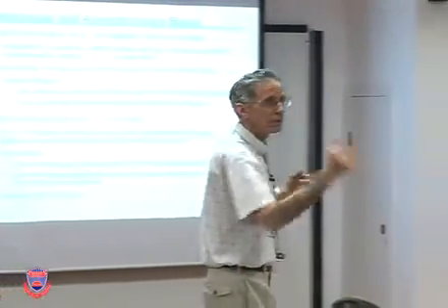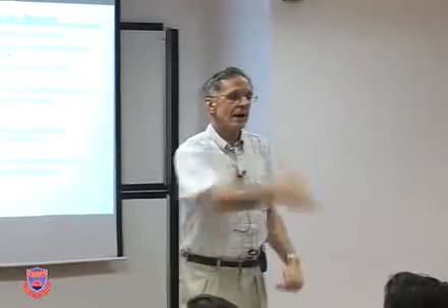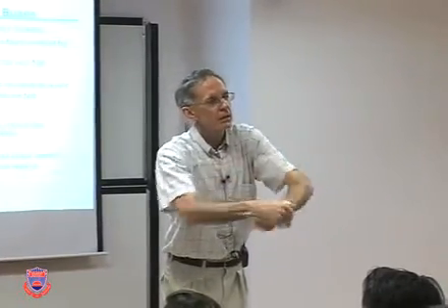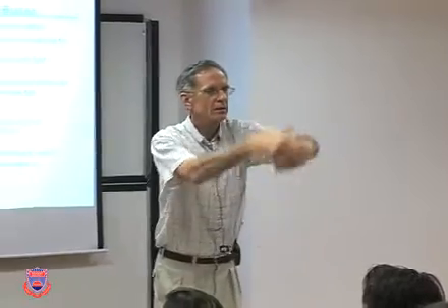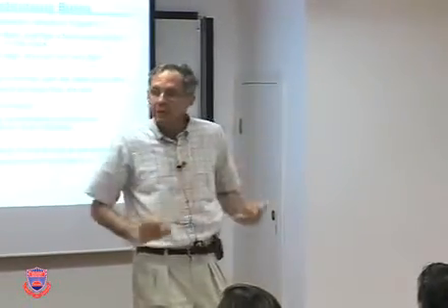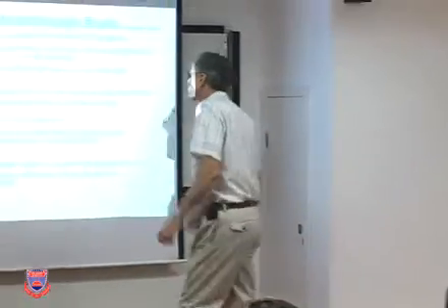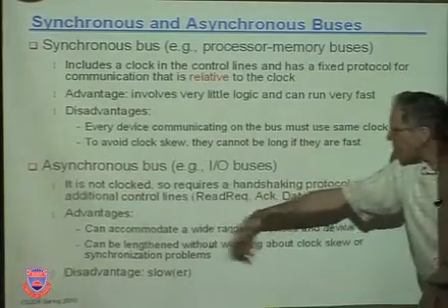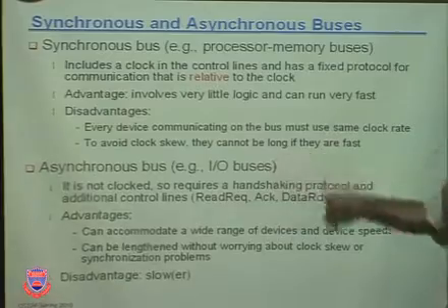Now you have handshaking protocols. I'm fast, you're slow, hi. Okay, I'm ready to take your data. Okay, here it is. Okay, we can do that. See, so now you can have devices with different timings be able to communicate data to each other. It's not clocked. You have a handshaking protocol which would involve, I'm ready to read, okay, the data's ready, okay.